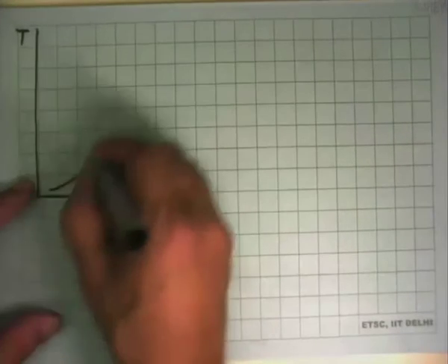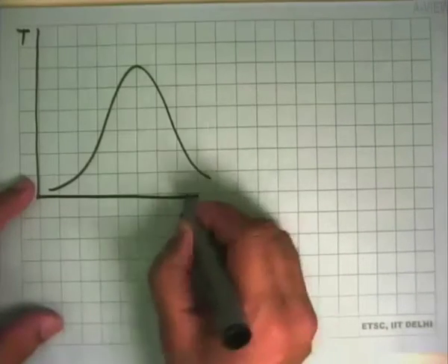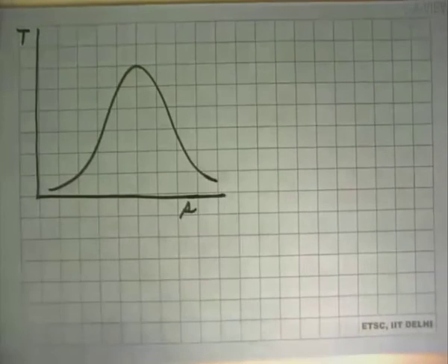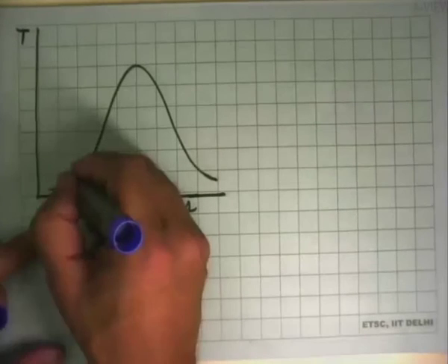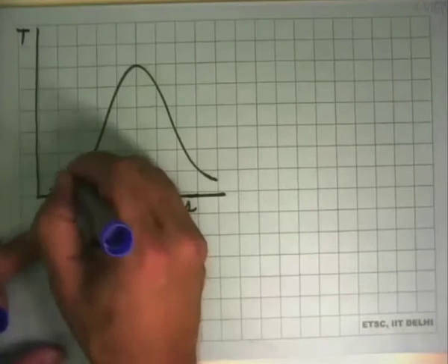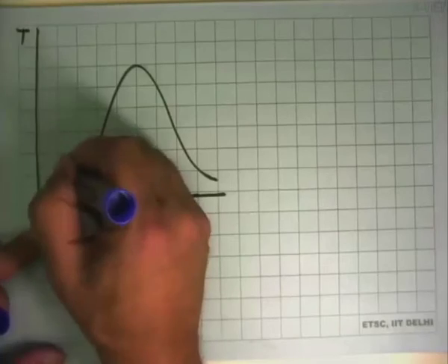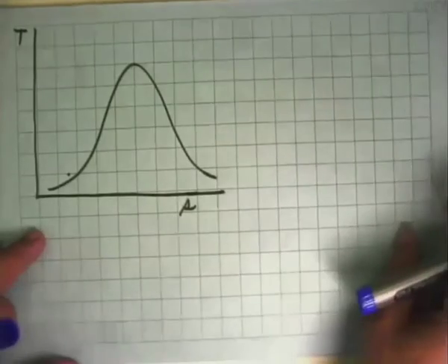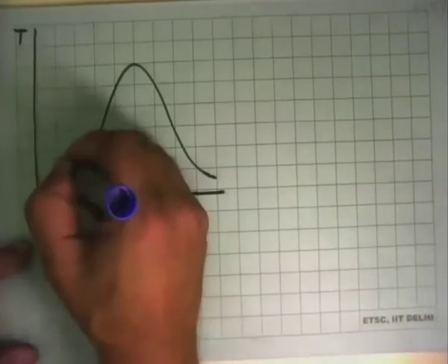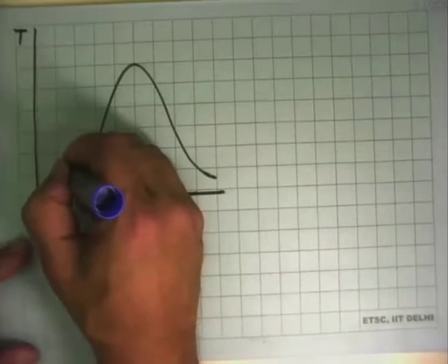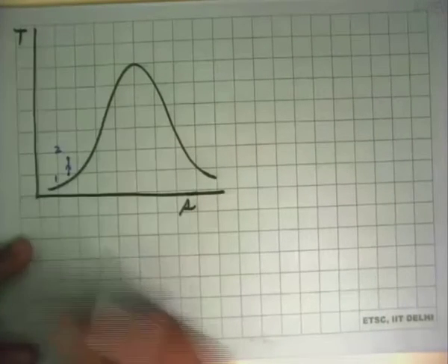Okay, now let's look at the T-s diagram. I said we are pumping water at ambient conditions, and we know that ambient water is slightly compressed liquid, and when we compress it, the pressure goes up, and in the ideal case it is adiabatic, and if it were reversible it will go up over there, and this will be 1 to 2.